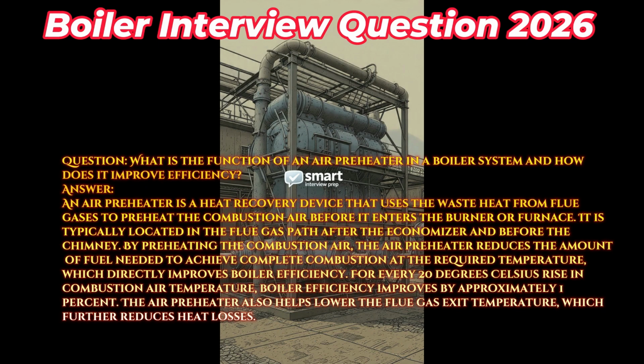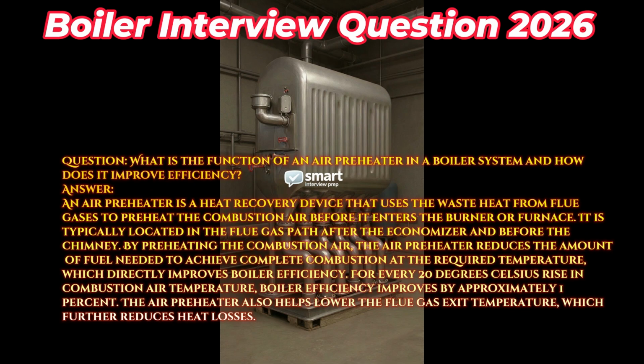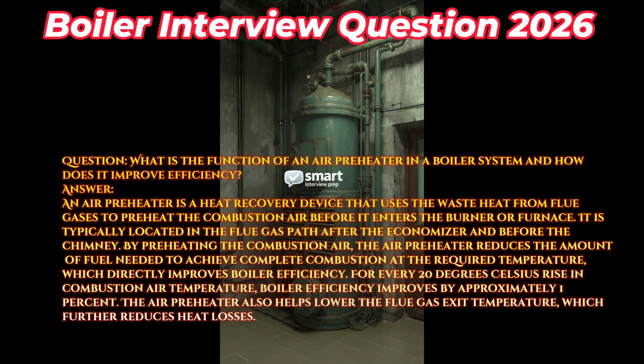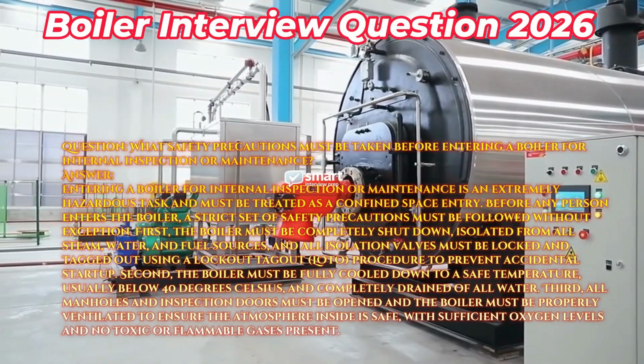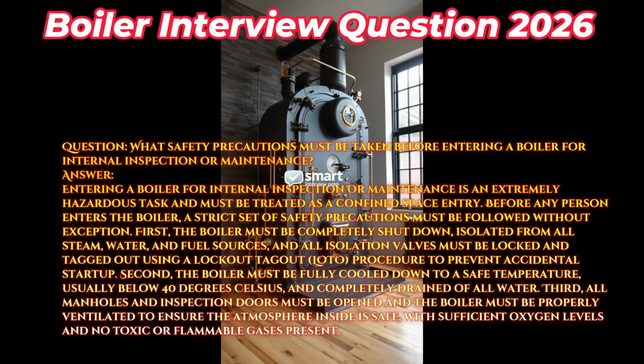For every 20 degrees Celsius rise in combustion air temperature, boiler efficiency improves by approximately 1%. The air preheater also helps lower the flue gas exit temperature, which further reduces heat losses. Question: what safety precautions must be taken before entering a boiler for internal inspection or maintenance?